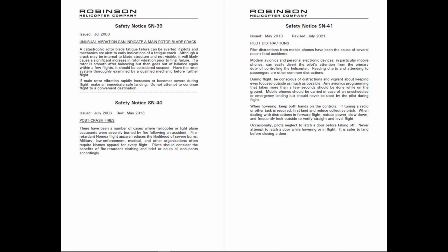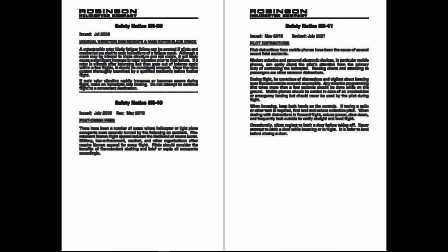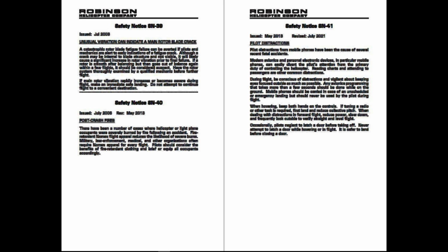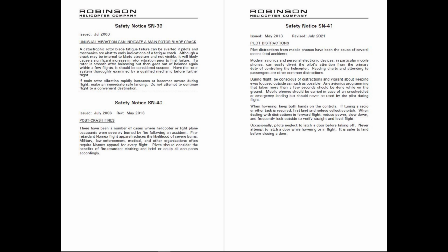During takeoff, while in a hover, the pilot notices one of the doors is unlocked and unlatched. What should the pilot do about it? The pilot should land and close the door, then take off again. Prior to takeoff, while in a hover, the pilot notices the radio is not set to the correct frequency. What should the pilot do about it? The pilot should land before changing frequencies, then pick up into hover again.